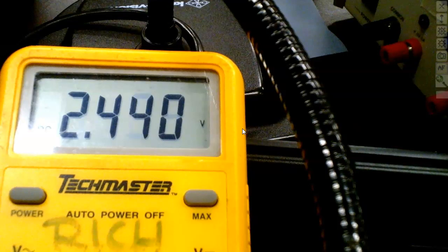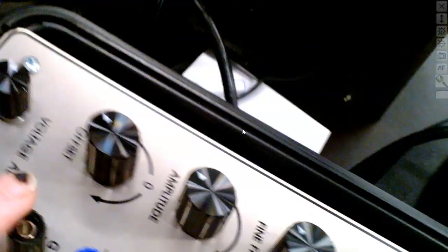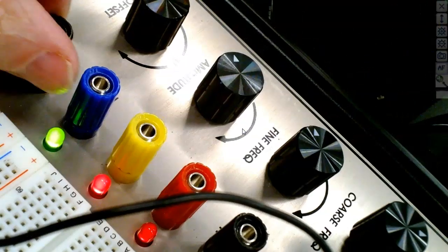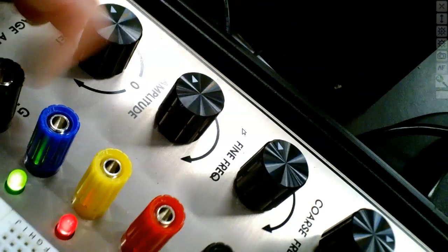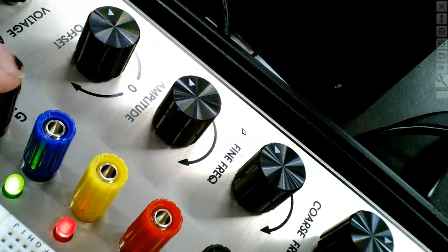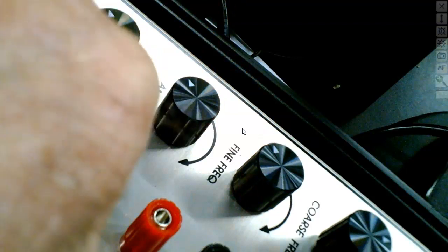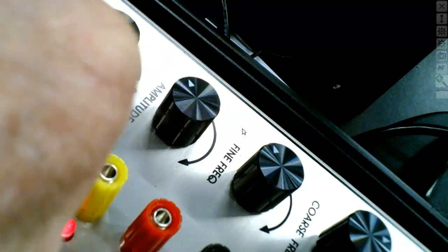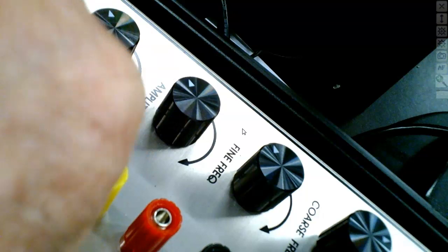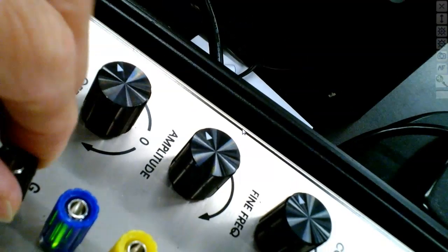Now, what I was doing wrong, I was using this guy right here. Ground? They call it common. It's not a ground, it's common. They call it ground, but it's common. If it was a ground, I could take an ohm meter and measure from here to the stop on my power supply, and it should measure 0 ohms. This transformer is totally isolated from this right here.